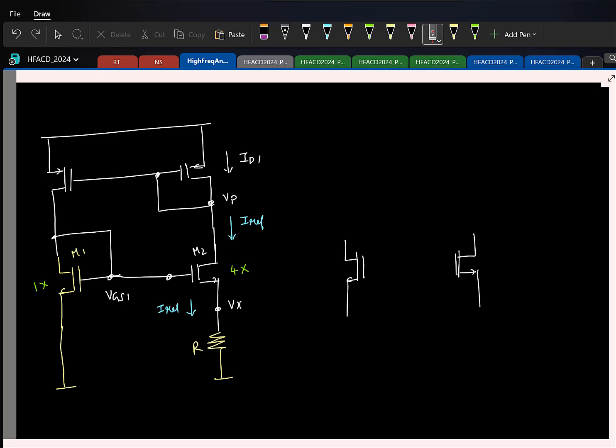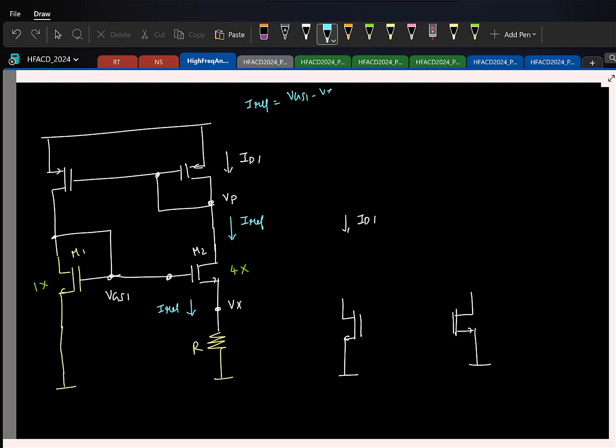What is one trivial potential I can connect the source to? I can also connect it to ground, right? I mean, this is fine. Again, assume that drain current ID1 is flowing in the transistor. So again, the job is the same. I need to generate this voltage. So first I'll do a diode connection. Let's say I make a nice diode connection like this. So this is VGS1. And as usual, if I have an infinitely wide transistor here and pass a current, this will be VTH1 ideally.